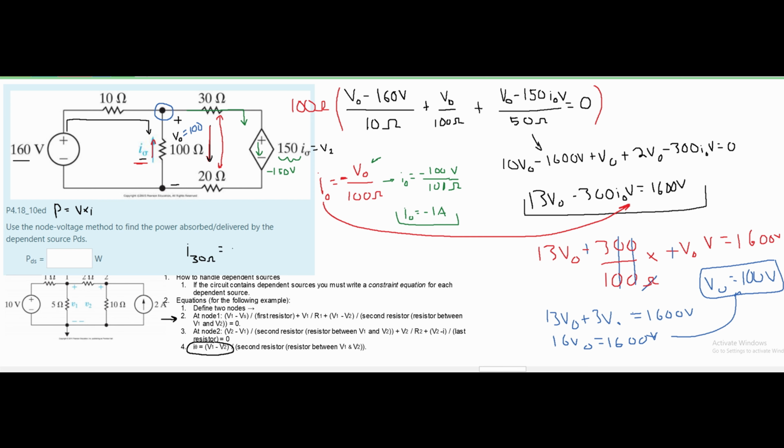And we're going to set this equal to our V1, so the voltage right here, minus our V2, which is the voltage in this side, over the resistance that it's over. And since it's in series, again, this is over a 50 ohm resistor. We found this V0 to be 100, so we're going to have 100, and this will be minus a negative 150, and up here it's all volts. Volts over ohms is again amps. We're going to add these two together, so we're going to get 250 divided by 50, and this is going to give us a current of 5 amps.